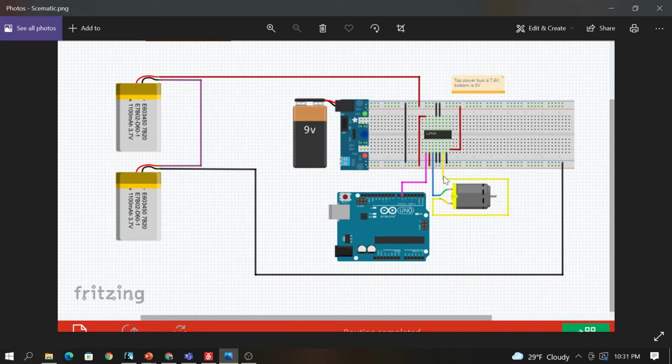Now, here's what we do. I set this pin here. It goes into the first register, because that register is going to control the input and output for this side of the H bridge. We apply power to this. So this is Y1, and then the yellow one is Y2, and Y1 and Y2 are basically the outputs for the H bridge, which are going to go into here.